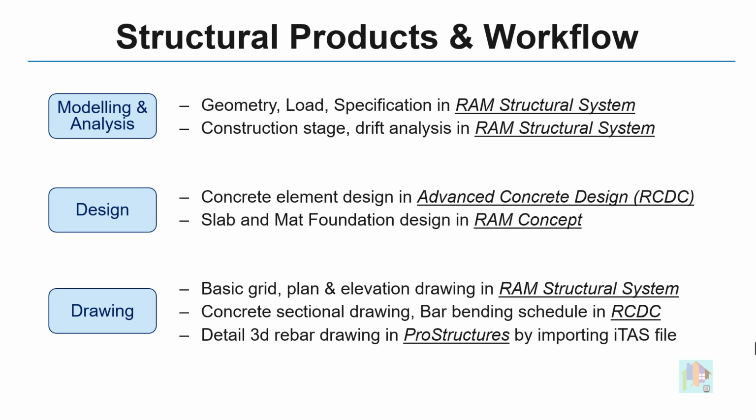In the RCDC module, all required concrete drawings are generated along with BBS. Similar drawings are generated in RAM Concept. For 3D rebar arrangement and drawing, ProStructure is used. Model data can be forwarded to this module using an iTwin file.